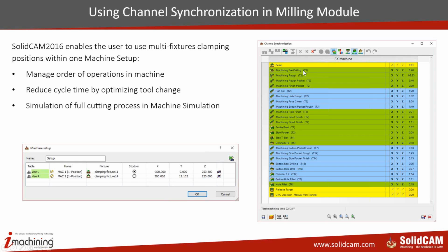And here we have, like, the green, it's my first part. The blue, it's my second part. And I'm synchronizing in that way to have synchronization order to follow the same tool, as you can see over here. So we have tool number 2, then it will move to the second part. Then we have tool number 3, it will go to the second part, and so on and so on.